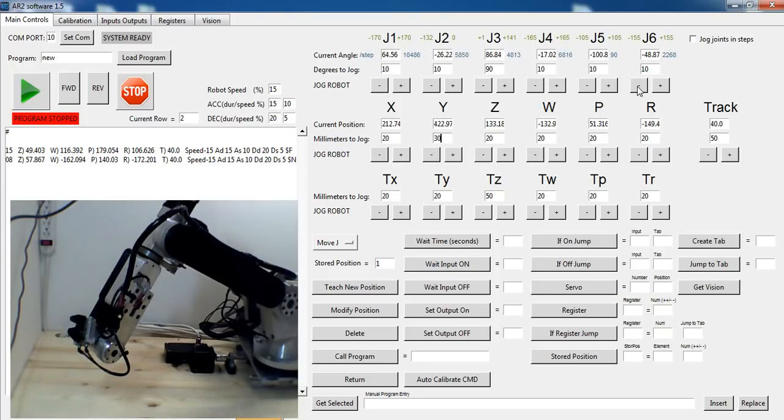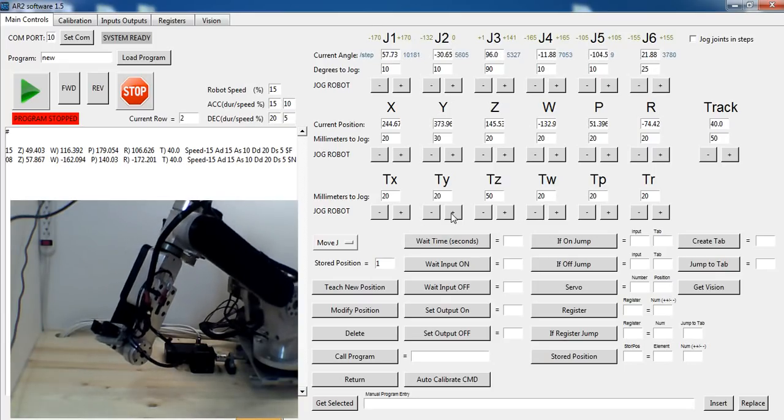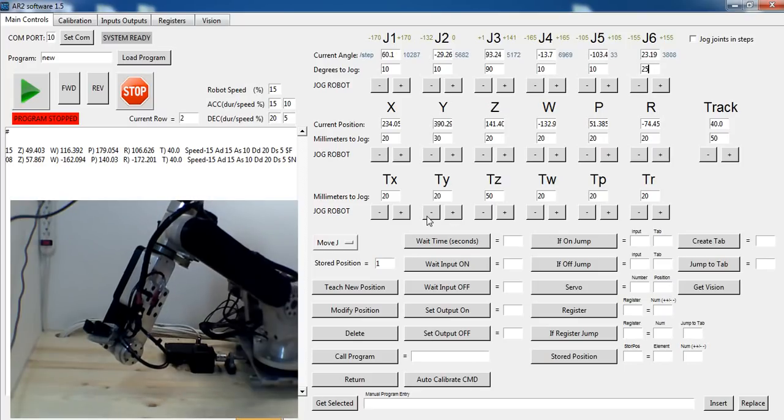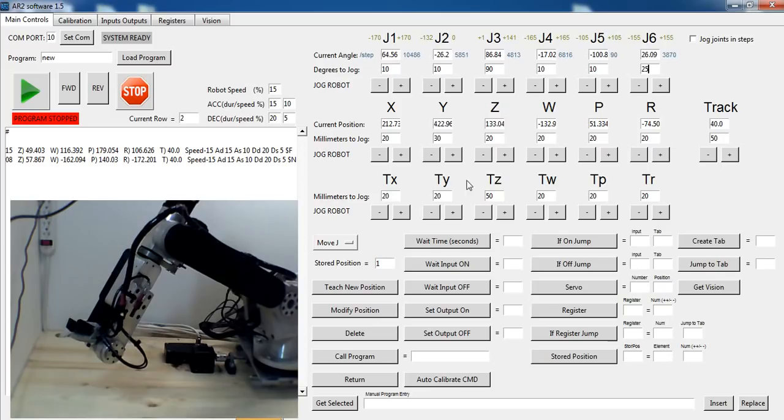And if I rotate the gripper, let's use joint 6 to rotate the gripper a few degrees. Let's go the other way. So now I've got the gripper going a different direction, and now when I jog, you can see it's going to move in the direction of the gripper. So that's what these are for. The yaw, pitch, and roll of the gripper are probably not going to be much more useful than the yaw, pitch, and roll up here. I still have some future work to do with those buttons there, but that's that part of it.